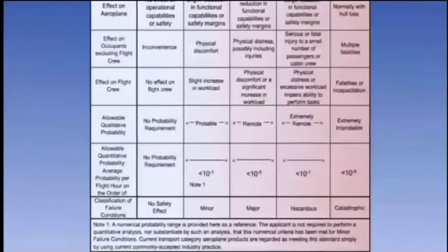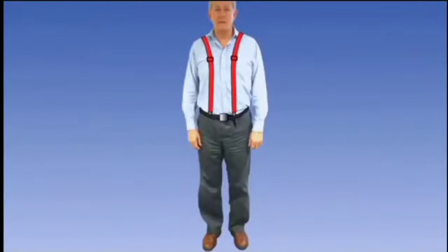The basic objective is to achieve this: a single failure of a single element in the system or subsystem of an aircraft must not be catastrophic. A second failure in the same subsystem on the same flight should not be catastrophic unless its joint probability with the first failure is extremely improbable.